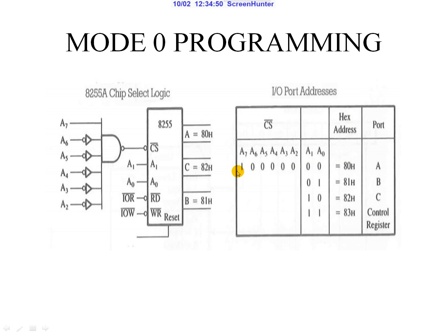So if you need to access port A, then the hexadecimal address is, we can segregate 1000 as 8 and 0000 as 0. So we can access port A at 80, 81 hexadecimal address is port B, 82 is port C, and 83 is the control register.